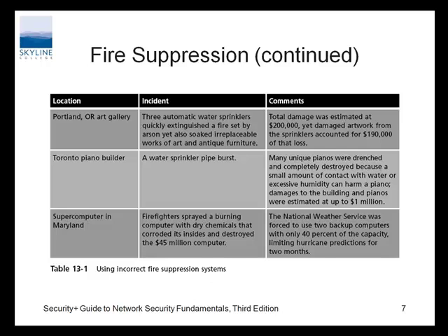What's the best way to put out a Class C fire? With a Class C extinguisher? What's the best way to put out a Class C fire? Turn off the power. If you take the power off, because what is a Class C? It's an electrical fire. If you don't have any electricity, can you have it? Now, you may have a residual Class B, probably a B because they're usually poly, some sort of plastic around the insulation may be burning.